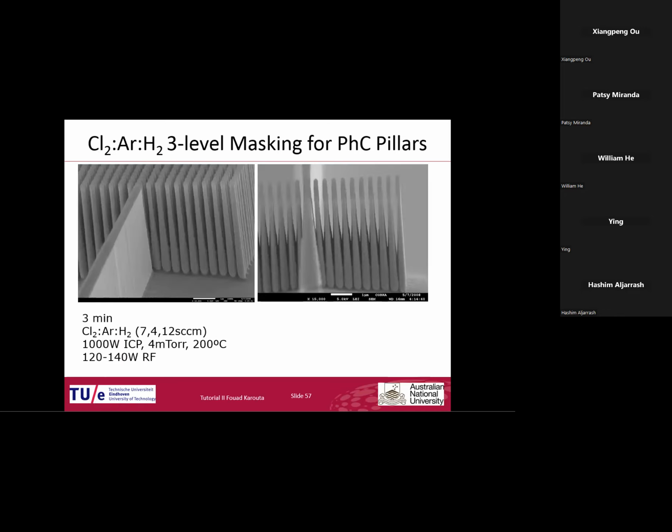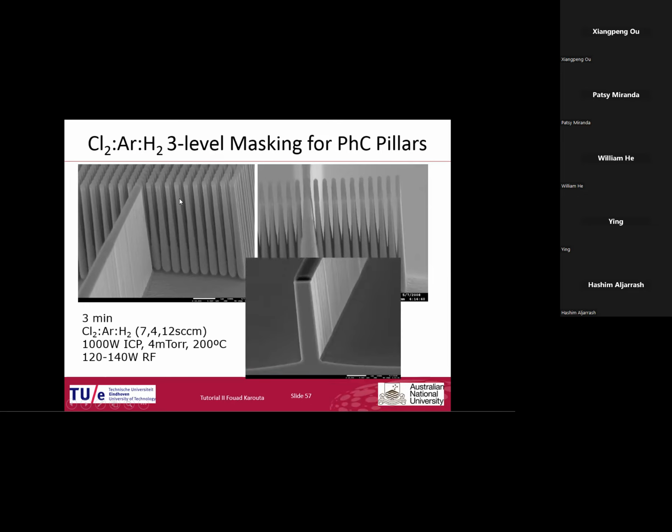Now we use this technology to help another student to do photonic crystal pillars. And so you see here, we have very deep etching, about 6.5 micrometers. Of course, with the pillar, you don't get the same shape, but still, if your device is at this level, you have enough contrast to get it working. And this was the waveguide on the edge. You see, quite smooth.